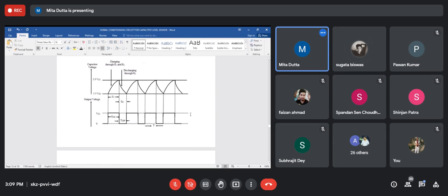In the output voltage, the capacitor will gradually charge until it reaches 2/3 VCC. Yes, the output voltage will be what I have shown you. So when the voltage across it is greater than 2/3 VCC, the capacitor will discharge. This depends upon the two comparators, how the comparators inside are connected, and the output from the flip-flop.